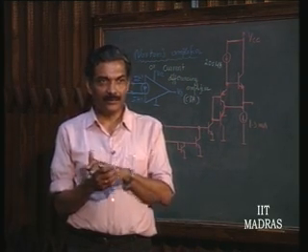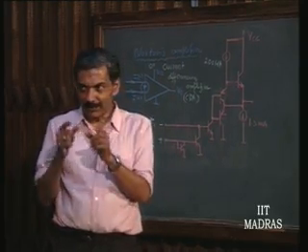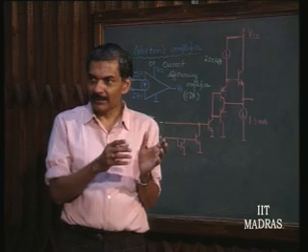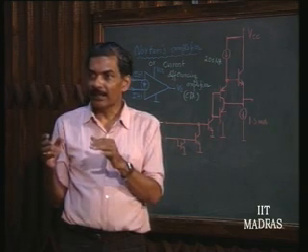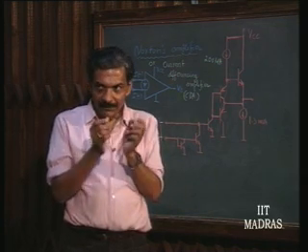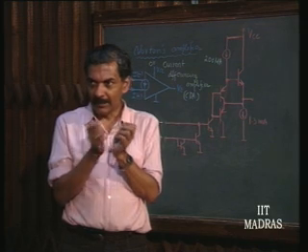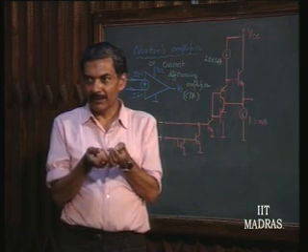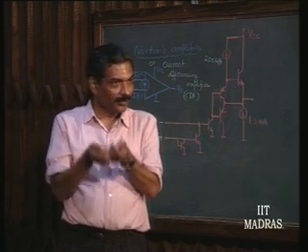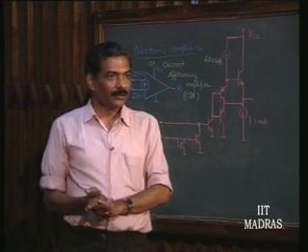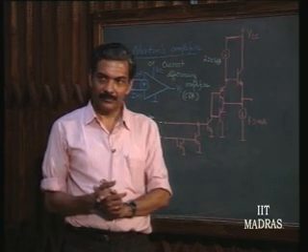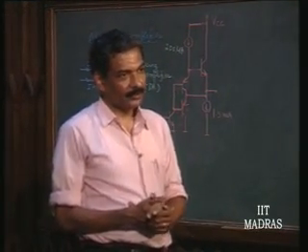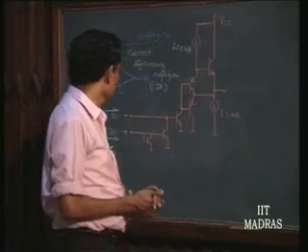Here it is the dual of this. Why use V1 minus V2 as the difference input signal? Instead, we will use the dual, which is I1 minus I2, or I minus minus I plus, or I plus minus I minus. Current differencing. The difference between two currents I1 and I2, let us say IA and IB, is the one which is amplified, fed as input to a transistor base, which is automatically amplified by beta times, etc. Again beta times maybe another transistor stage like that, and appears as an output voltage. So, this is called Norton's amplifier or current differencing amplifier, CDA.